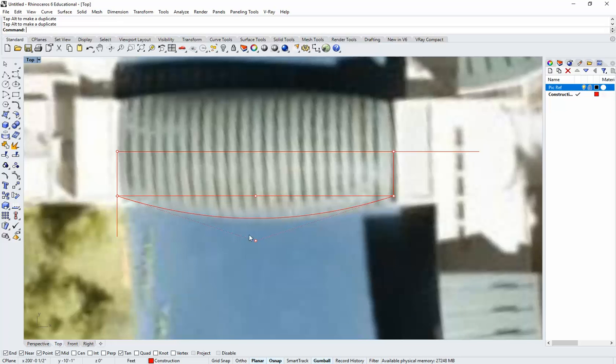Okay, now in order to set the overall width to make this a symmetrical roof canopy at about 80 feet wide, I'm going to find the midpoint of that curve, which I can snap to, or to be 100% accurate, just in case there's any goofiness in the line, I can draw a construction line out this way, find a point at my intersection, which should be right at your midpoint, no problem.